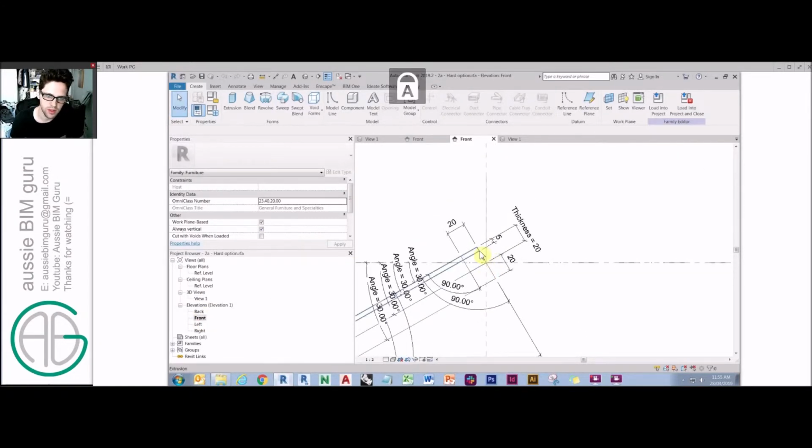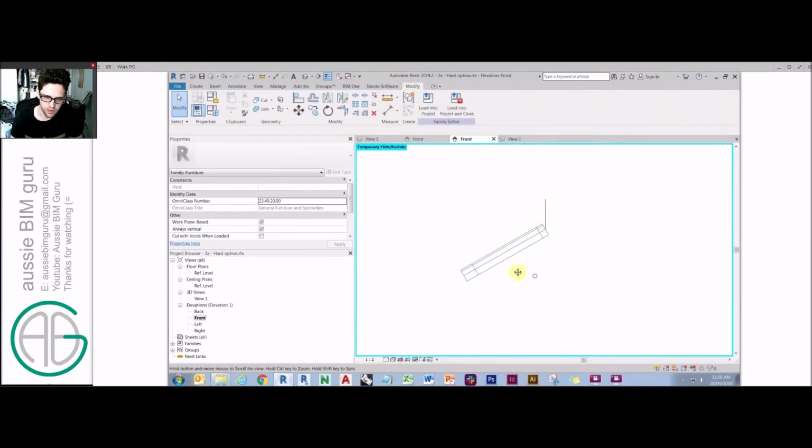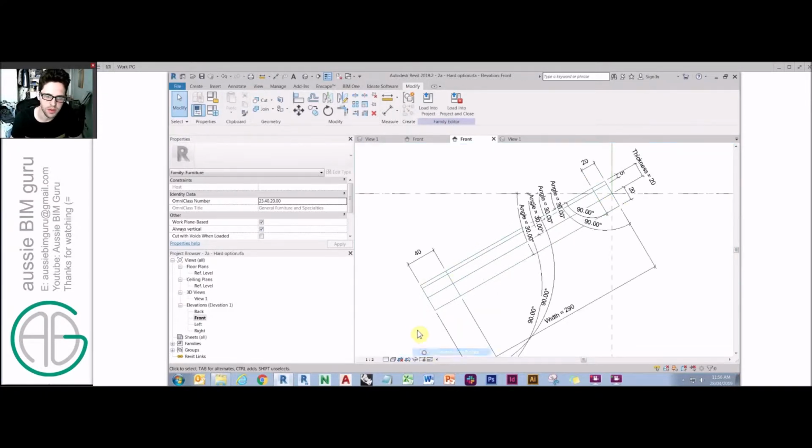So essentially what this is a whole set of reference lines. So these are all reference lines. This line represents the strut in this zone. This zone represents the strut in the closed position, and this is the table with the laminate thickness on top. And you can see from there I've had to assign angle parameters between each reference line and here. So as these all adjust, so will all of these reference lines rotate around this point.